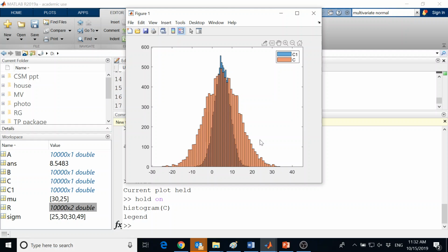Because if you want your design to handle, say, 90% of the cases of the workflow, you want to find the 90th percentile of this delta distribution. If you don't consider correlation and just do the C, you're going to be designing for somewhere around here, maybe a delta of 25, a water level difference of 25. But if you consider the correlation, you'd only be designing for C1, the 90th percentile, which is like 90% of the area here, 10% here.